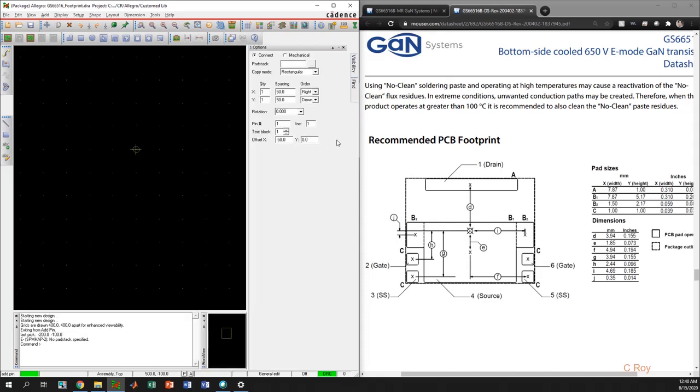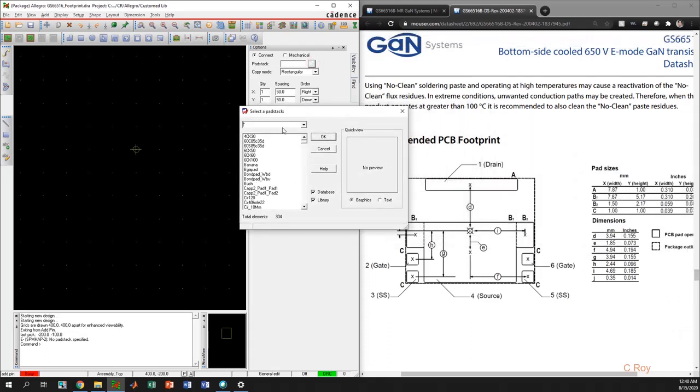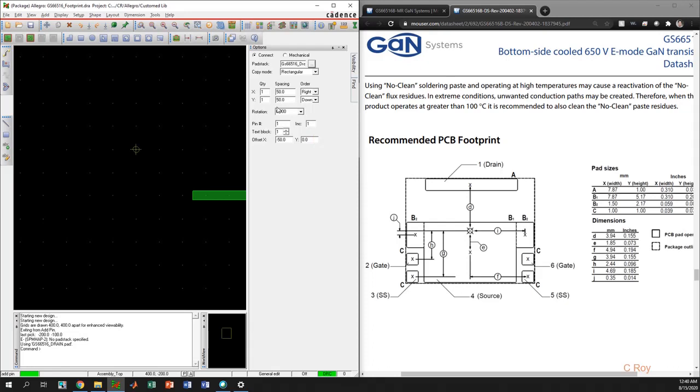Okay, here in this padstack option, we have to select the padstack. So let's select the pad that we created. It starts with Z. So this is the drain pad that we just created. So select this drain pad. Now here pin number is 1. Everything is fine. Let's place it at the right coordinate that it needs to be.